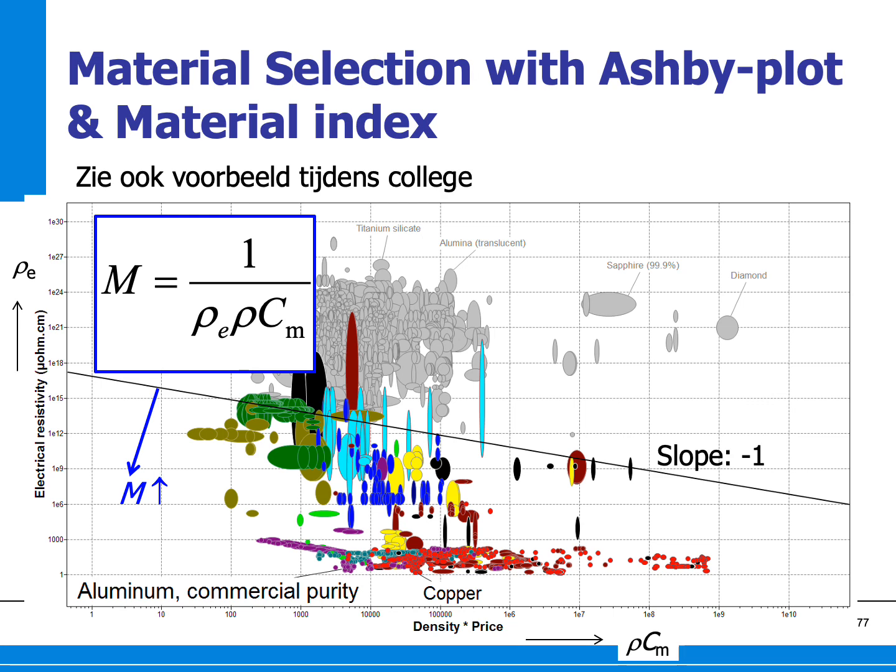The energy stored in a capacitor is given by this formula. If I apply it to this capacitor, I can see that it can store a maximum of 11.2 joules. In certain circumstances, that's enough to do some serious damage. Now, the ultracapacitors I bought are 2,600 farads, and that's not a mistake, 2,600 farads, with a maximum of 2.5 volts. That means that one of these ultracapacitors can store 8.1 kilojoules of energy, which is a ridiculous difference.